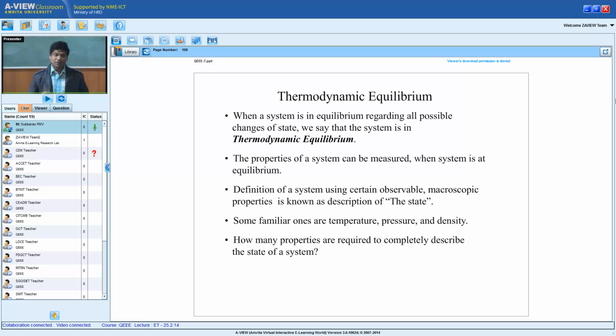So the zeroth law talks about only thermal equilibrium, but gives an idea that similarly many equilibriums can be established. When it comes to the thermodynamic equilibrium of a system, there is nothing happening thermodynamically to the system, which means all possible equilibriums are achieved. I can say the system is in thermodynamic equilibrium with the surroundings if and only if thermal equilibrium, mechanical equilibrium, chemical equilibrium or any other equilibrium which is important to that particular thing. The breadth of thermodynamic equilibrium is much more than the zeroth law. Why doesn't the zeroth law talk about other equilibrium? Because there are many possibilities for the same kind of equilibrium. So very important. Learning the zeroth law much deeper is essential to become a good engineer in your life.